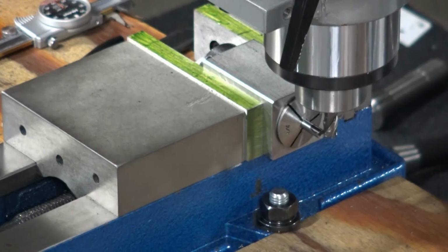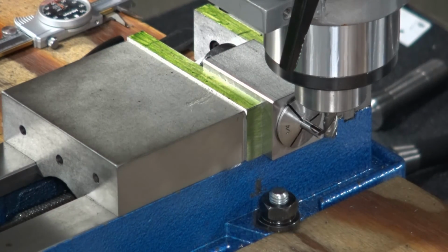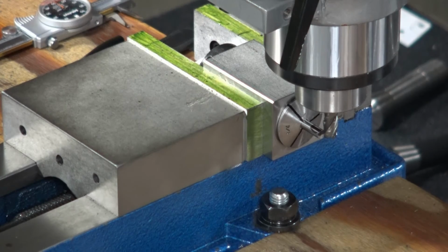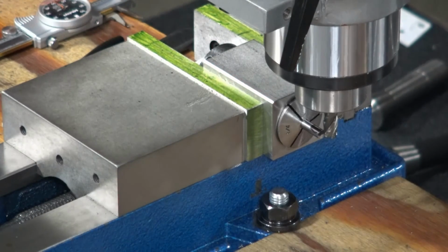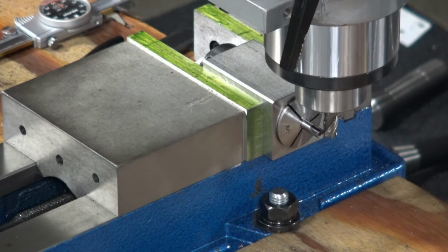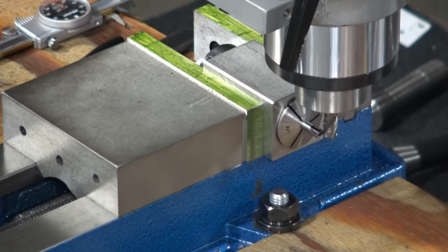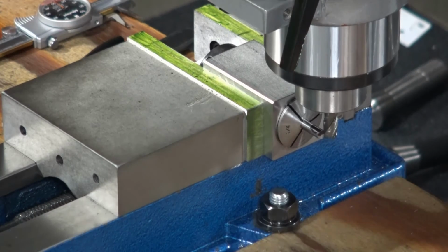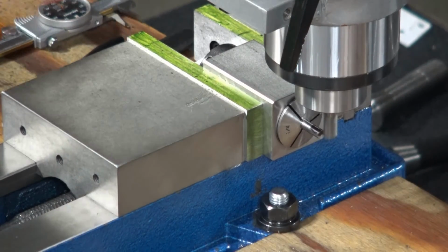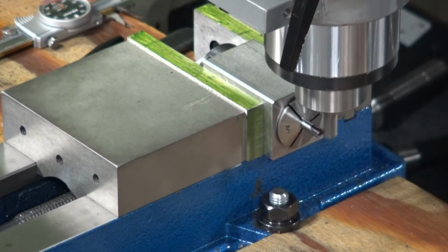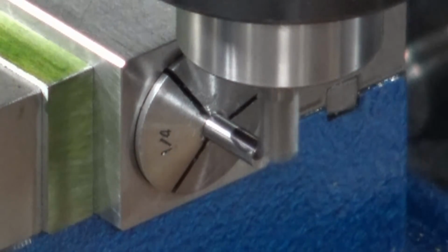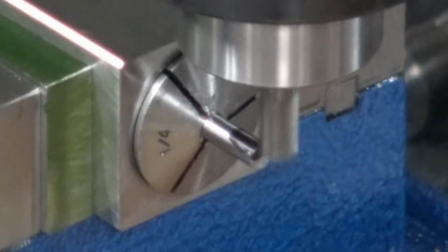So I'm going to use a touch off where the machine's running and I come in and just touch the end. Now there's a couple of different senses that you can use, right? You can hear the cut. You can see the cut because I colored the end, right? And you're going to be able to feel it in the machine. I can actually feel it turning the hand wheel. So what do we have to do? We have to calculate our RPM. You guys are going to be running slower than what I am because I have a carbide end mill. So we're on our top speed, so I'm going to be comfortable with that 775. We're on low range. I'm going to come back around the back so that you can actually see on the front. And all I'm going to do is come in till I just hear and feel it touching. Okay?